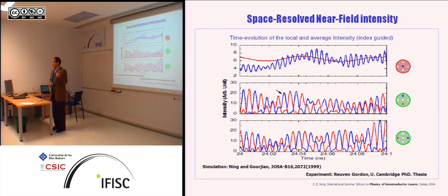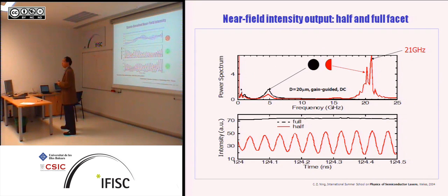So if you collect this way and do high-speed modulation, you get very fast modulation, much faster than the few gigahertz you can do otherwise. This is a pretty simple experiment. If you have a 10 micron or 15 micron VCSEL, we can, for example, roughen part of the output facet, or just use imaging or fiber coupling to collect just part of the output.